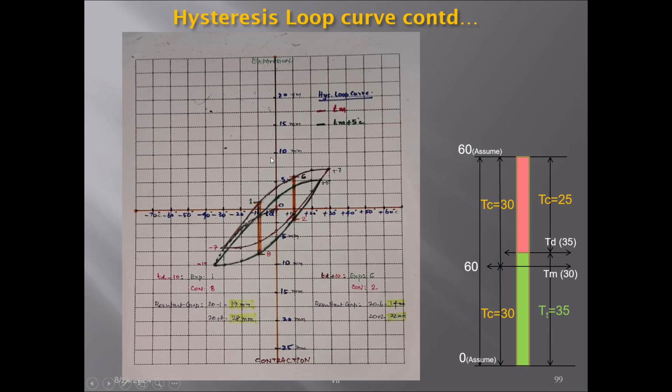This is the range we are actually able to get by plotting the IRSE loop curve. This is the way, for various temperatures, various zones and rail sections, that gaps have been calculated using the IRSE loop curve, and the detailed table of range of gaps has already been framed.